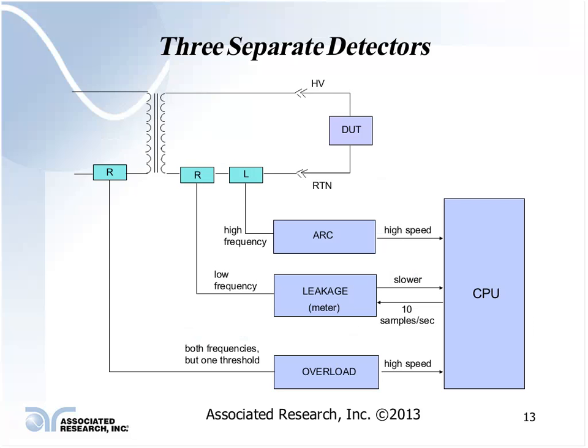It allows low frequencies to go through and only looks for the high frequency noise that is being generated due to an arcing condition. And it's on a high-speed shutdown, so it will detect a failure within 400 microseconds and shut down the CPU, if it sees an arc occurring.